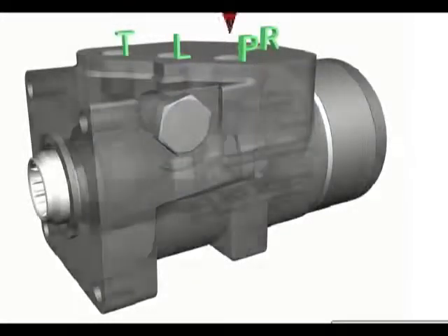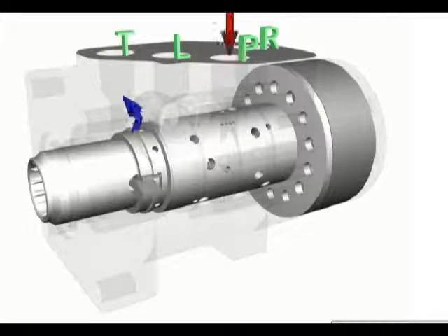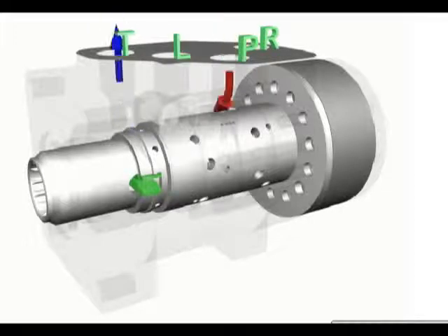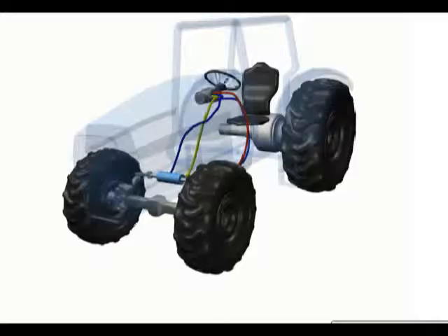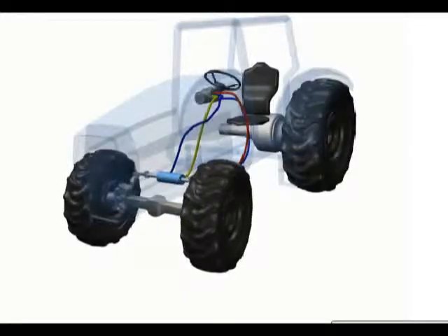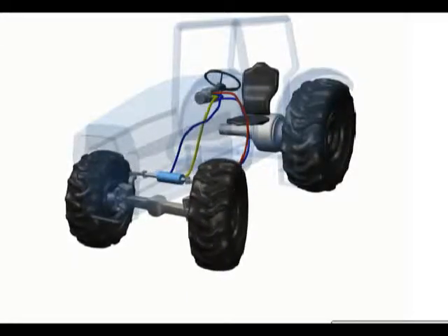Please refer to the motor section of this training for a better understanding of these designs. Without rotation of the steering wheel, the centering spring holds position of the spool and sleeve, and the fluid flow is allowed to pass through the pressure port to the spool and sleeve and to the tank port of the steering unit. Rotation of the steering wheel counterclockwise rotates the spool in the sleeve against the force of the centering spring, allowing fluid to pass through the rotating spool sleeve valve.